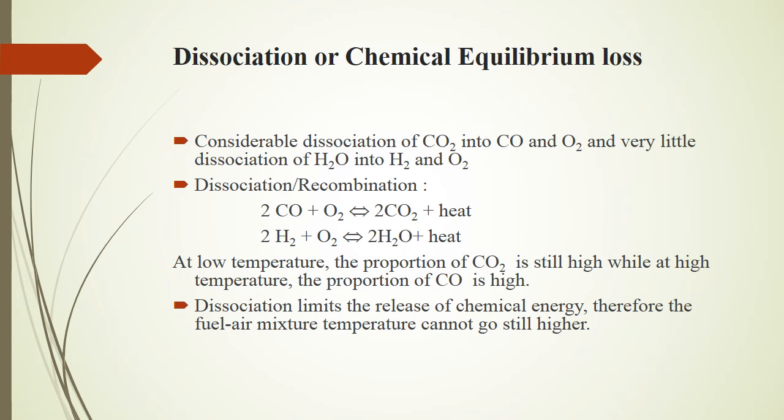In IC engines, mainly dissociation of CO2 into CO and O2 occurs, whereas there is very little dissociation of H2O. The arrow in the above equations is in both directions. It means a limiting temperature is attained when the reaction has the same rate for either direction. The reaction is then said to be in equilibrium, that is, definite proportions of CO, O2 and CO2 are present in the equilibrium mixture at each temperature.